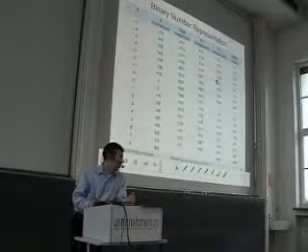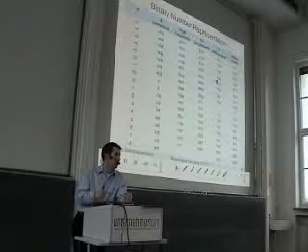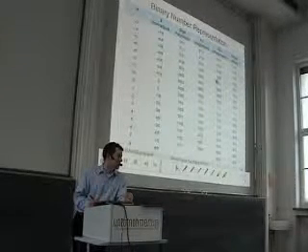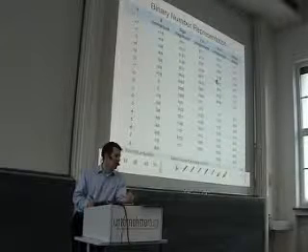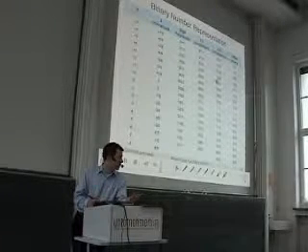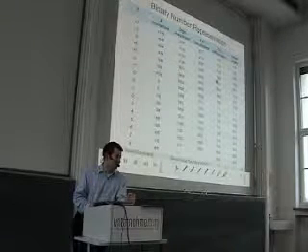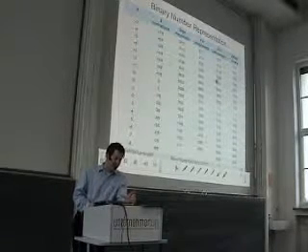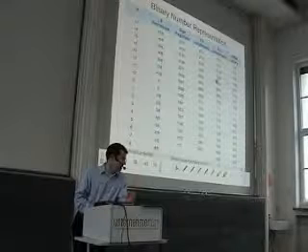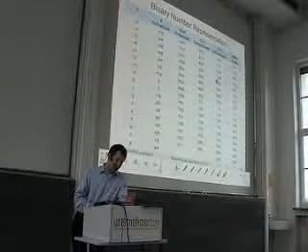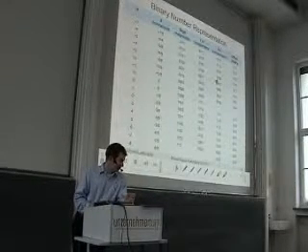Sometimes there is the 1's complement representation. There this plus 1 step is missing. So in a 1's complement system, coming from a positive number to a negative one and vice versa is just inverting all bits. In mixed signal systems, namely in ADCs, there are often different number systems used.